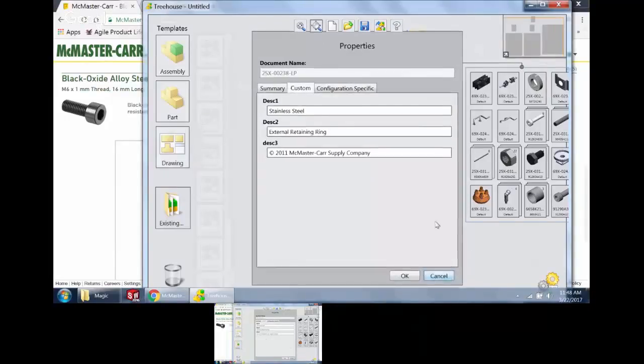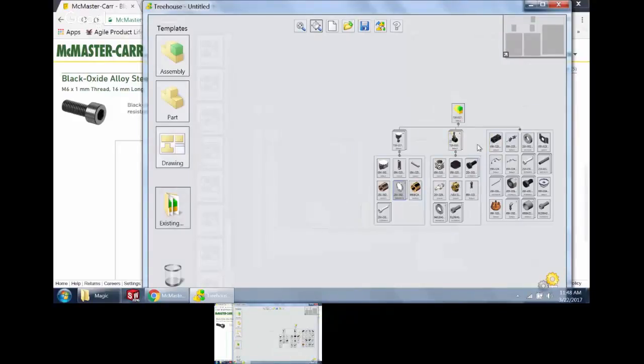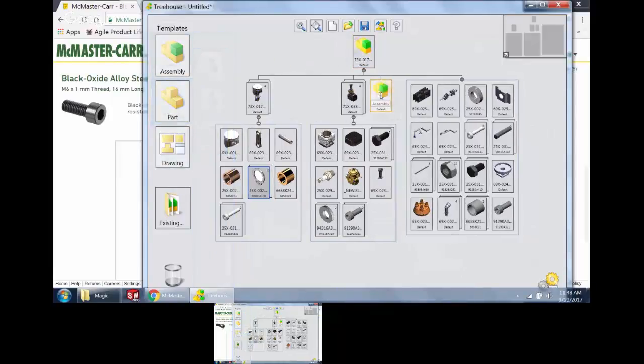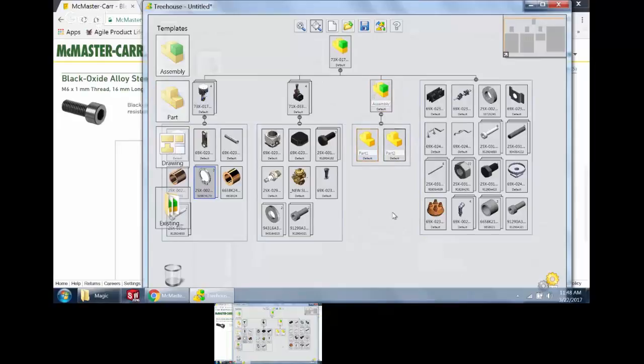You can even put in custom properties from this level if you want to make sure all your metadata is there. But it's a good way of getting an overview of seeing what's going on. So you can use it to look at an existing plan. And like I said, you can actually add plans to it. If I wanted another subassembly, I could start fleshing that out, start naming those parts. It'll actually create it. Where it's going to drop it is origin on origin. It'll just drop it into that top level assembly as a subassembly in that origin, on the origin of the top level assembly.